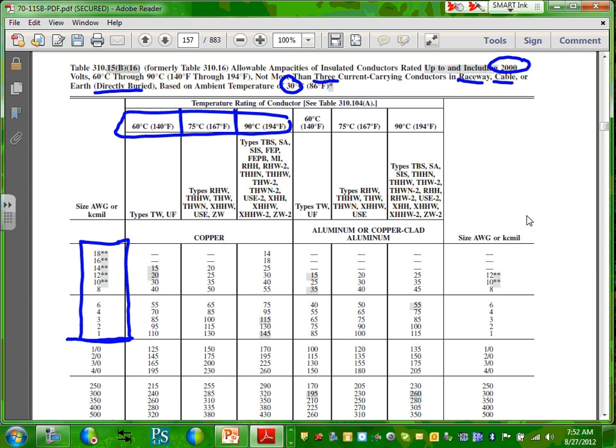So now let me tell you what you're going to be doing. You're going to be almost always using insulation rated, especially commercial, for 90-degree. Almost always. Why? Because then when I derate it, I can get more amps out of the conductor. So don't even think of going there in terms of size of the conductor. THHN is notoriously famous. THW-2 here, THWN-2, XHHW. These are typical insulations that can give you, in a wet location or in a damp location, a 90 degrees Celsius rating for the temperature of the conductor.